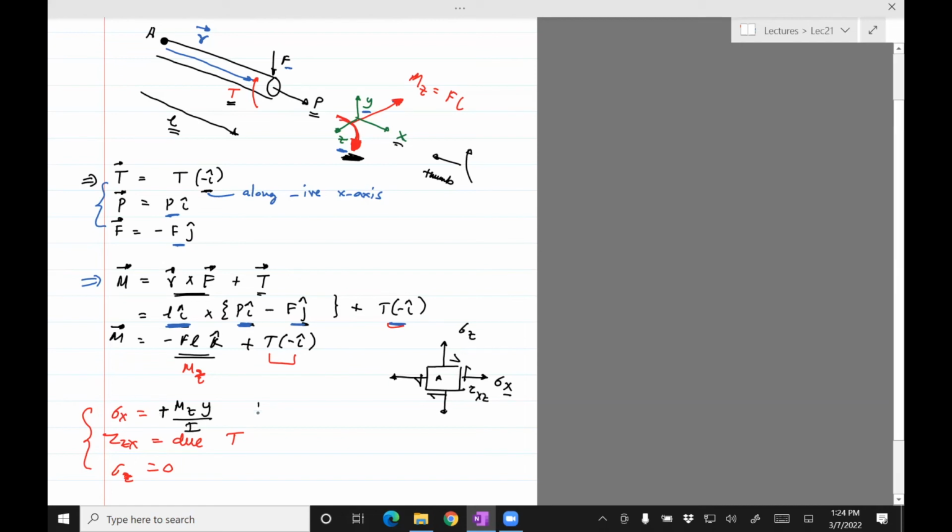And then P divided by A is the stress due to axial load. And we know that that stress is positive no matter what, right? It's always stretching, it's not compressive. So that stress is also tensile. In fact, it's tensile for the top, and it's also tensile for the bottommost layer, which is positive.